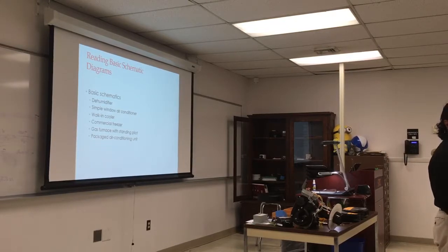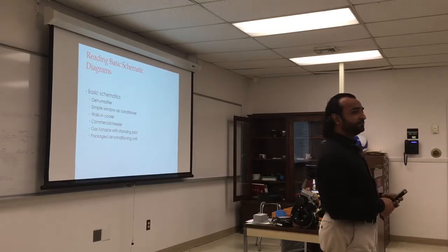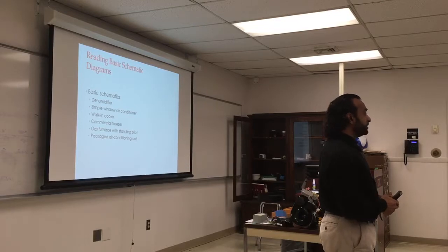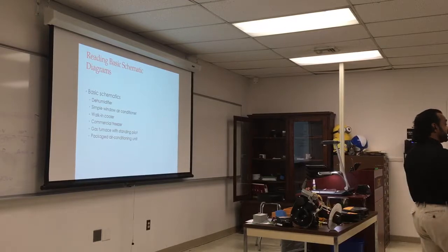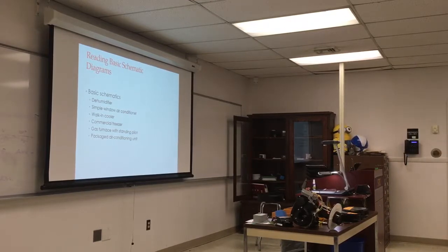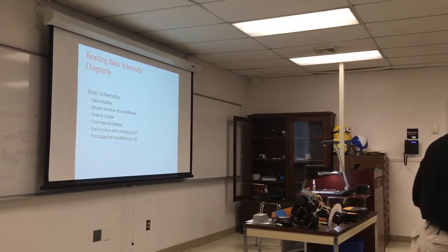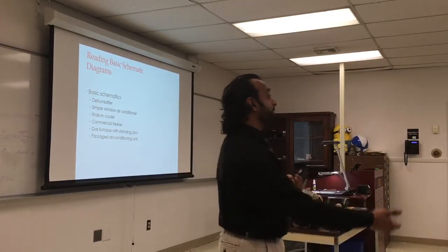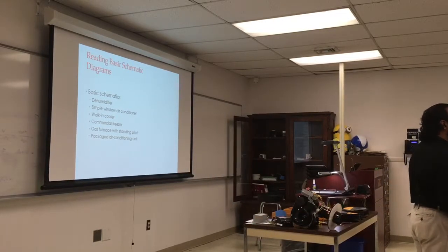You'll need more refrigerant. Did you use the gauges yet? What gauges? The refrigerant gauges? For ACs? Yeah. We did it. It was like our first lab, I think. Yeah. Okay, good. Excellent. So this is a very, very important skill, because again, not a lot of people know how to use that. And Bill is very good at it. It tells you how to refill. How do you know not to overfill the system? What happens if you overfill the system? What happens if it's underfilled? And what happens if you think it's underfilled and you fill it more? So it's very, very critical to know these skills.